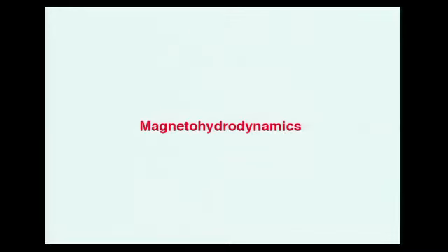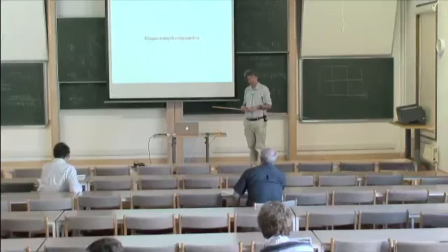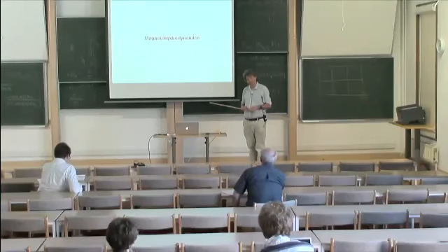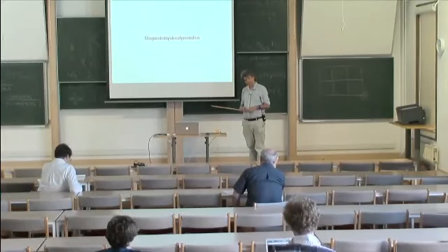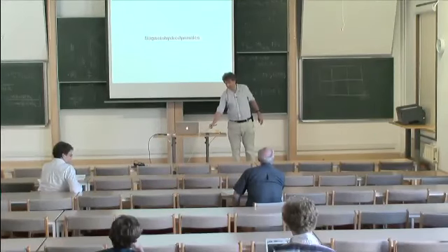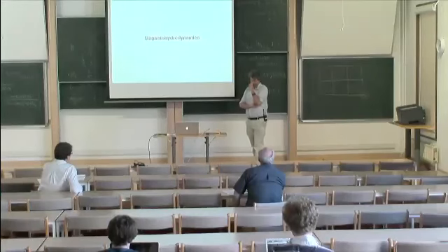Maybe before you do that, the viscous stress term in Navier-Stokes is second order in space derivatives. The stress is only first order. Stress. Yes. The divergence of the stress, it's second order. And that term is related to heating, viscous. Yes. So what I presented is just an isothermal model.